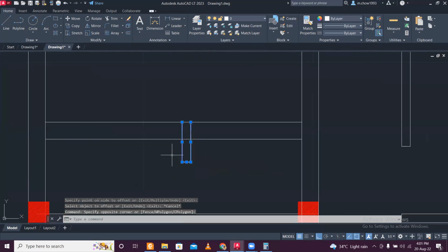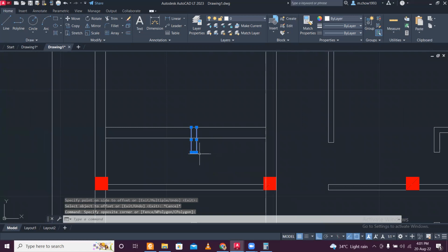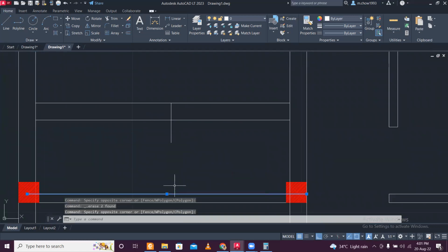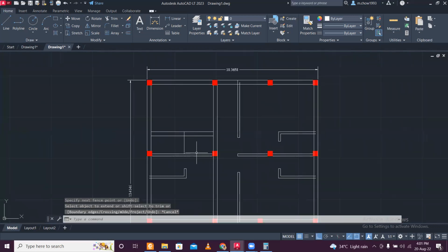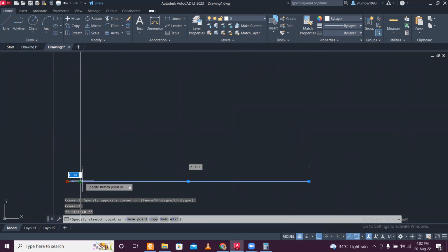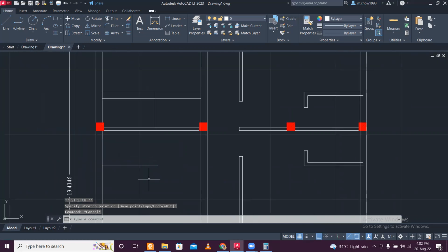And here we'll just take this, select extend center, and this one is on the same line. So what we'll do is just delete them both, change the line here and join it. You select this and extend center, join this, and offset of 250 mm.